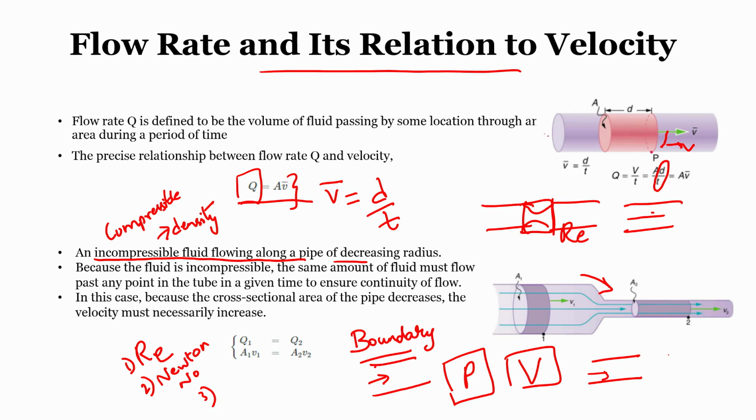So, here the channel cross section area remains the same, consider this to be a healthy environment. But what happens when the diameter reduces, that is the cross section area reduces? We know that the mass remains the same. So, from the law of conservation, the velocity drastically increases when the cross section area drops. The area decreases, velocity increases for the same fluid which is being driven through this channel.